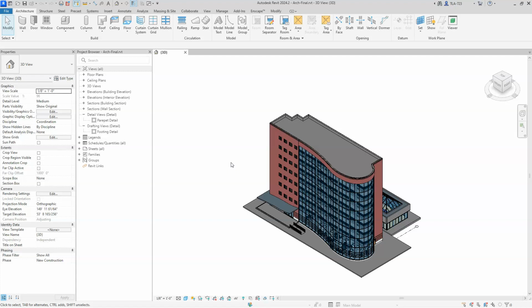First of all, be thinking about what the main differences are between AutoCAD and Revit. Remember that AutoCAD is a two-dimensional drafting tool primarily. Revit is all done in 3D. In AutoCAD, we're drawing the lines that are ultimately going to be represented in the sheets that we produce. In Revit, we're modeling, and we're taking from that model cuts through the building or images projected away from the building to generate our views. The primary advantage of that, of course, is that when you make a change to the building, all of the views that are affected by that change are automatically updated.